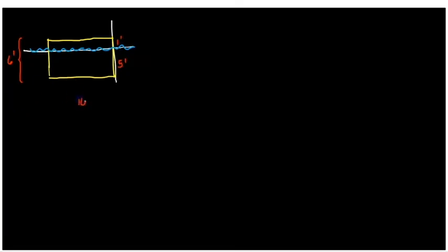The total here is still 10 feet. So let's draw the representative element. The representative element would be a horizontal element. So this one. And then when you draw the height, it has to be only what is the affected area. So this is the height. It does not start from the top because the top is not submerged in the liquid. This one would be the dH. In our case, that's just dy.